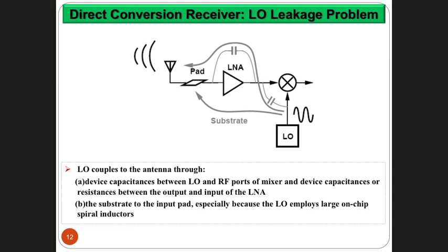It comes from something called leakage problem. Yes, it's because of the parasitic capacitance, the local oscillated signal generated from the local oscillator here can leak back into the input of your system. Not only that, it can actually even transmit around you, in an undesired fashion. The problem of leaking back to yourself is one thing, and the problem of affecting other transceivers is another thing. Affecting other transceivers is probably clear.